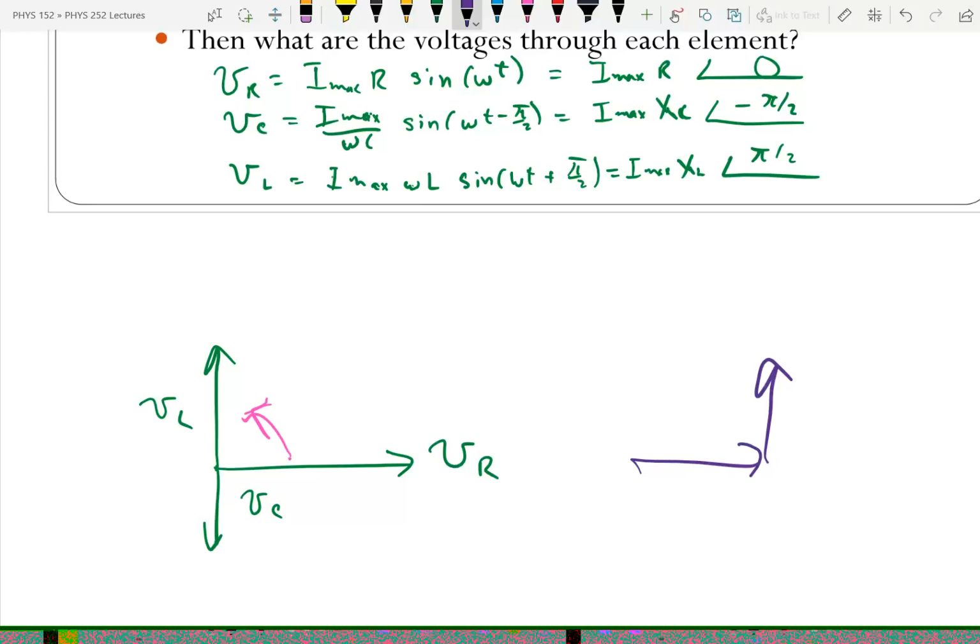There are two things that make inductors not perfect. One is that inductors are made out of wire that has a resistance that's not 0. So there's a little actual resistance in the inductor. If you measure its resistance, it's not going to be exactly 0. But much more importantly, our inductors are made with an iron core. They're made with an iron core because it makes the inductance much bigger for the same size inductor.